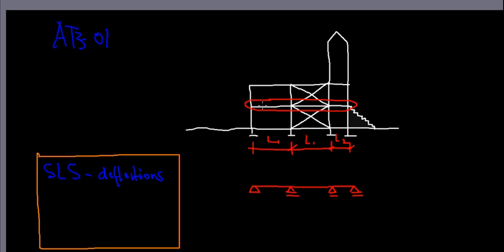Now with that established, we will have loadings to the slab. For now, and then we look at other loadings in a second, I'm just giving this little squiggle here, which is supposed to be the dead load of the slab. That's the permanent structural concrete or steel weight. And also the finishes. In this case, we call that super dead load. And these are really acting downwards all along the slab. So instead of drawing all these arrows, that's the more complete symbol, and two lines, you can just make a little quicker model here.